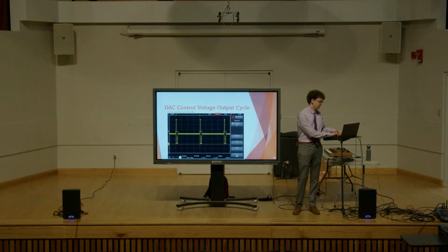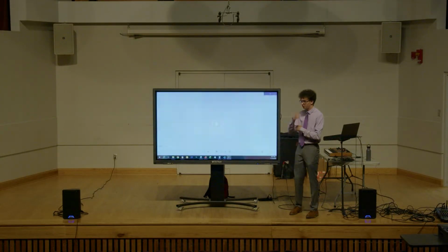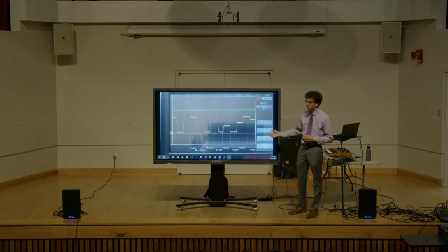So a closer look at what the signals will look like from your DAC are shown here. The yellow signals are the sequential control voltages, and the green signal is one specific sample and hold for the filter cutoff voltage. So it follows very well, and then you can see it doesn't droop or drain before getting re-upped by the DAC output. And so though you're only seeing one sample and hold here, each individual voltage level has its own sample and hold.